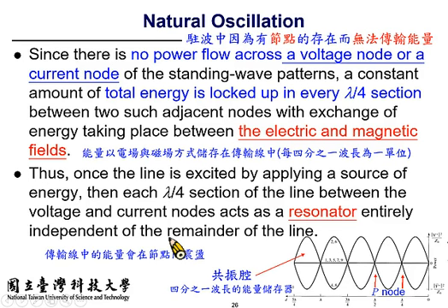Note that this short terminated transmission line is also referred to as natural oscillation due to the boundary condition, due to the presence of the signal. We observe that, as I already said, the presence of a standing wave represents that some of the energy is trapped on the transmission line.